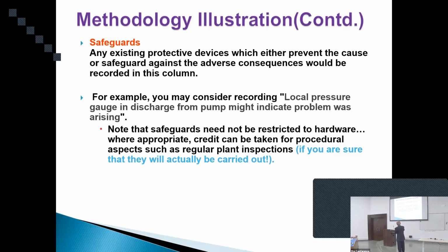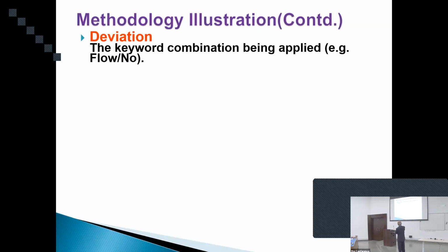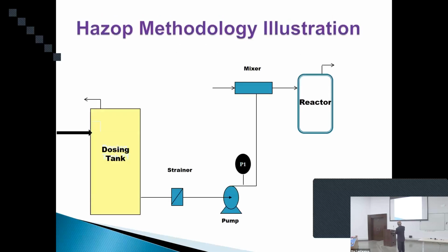Did you see that there is a PI, the pressure indicator, which indicates that pressure is low? When the pressure is not showing, that means it's not pumping. So this PI is indicating that there is no flow. Got the point? The instrumentation given for the whole process will guide you on what is available as a safeguard.